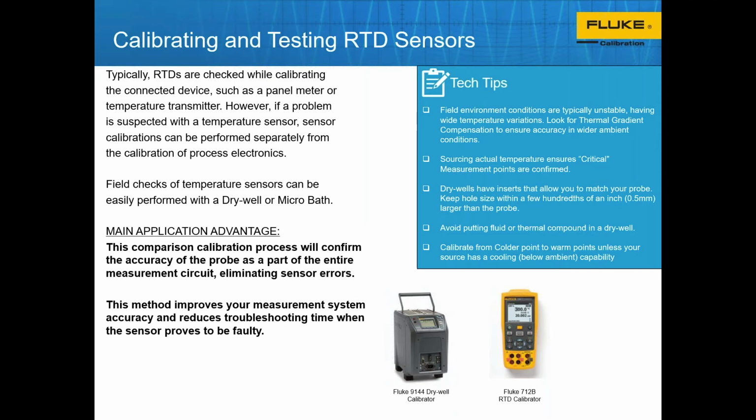The folks at the factory and the engineering side of our company have spent a lot of time looking at the material expansion rates based on temperature, and engineering in the air gaps that need to be there to be able to put a well into a dry block, heat it up, and then let it cool down and still be able to remove it during that process. If you decide to put some fluid on there, that fluid could get sticky or coke off and then seize that well into your dry block.